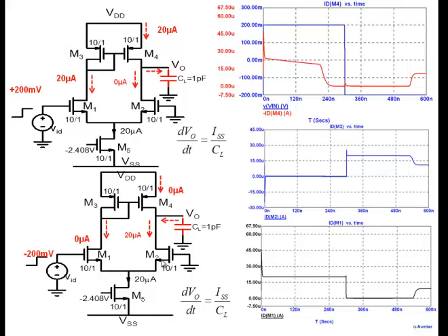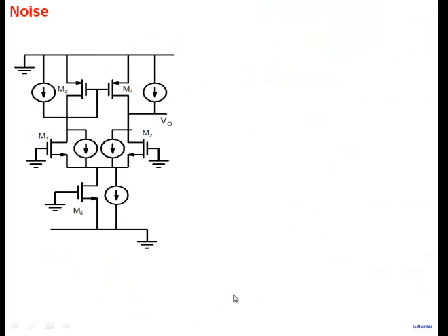So current switching does occur, but temporarily. As it goes into the linear region, then instead of 20 microamperes, it becomes less and this starts climbing because the sum of the two currents has to be the same, and eventually they both become comparable. All right. So that's the phenomenon that occurs when you apply large voltage steps, such that the current switching begins to occur here significantly. Okay. All right. One by one, we are going through all the parameters.